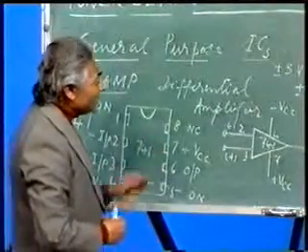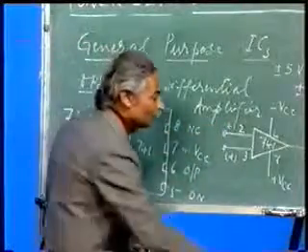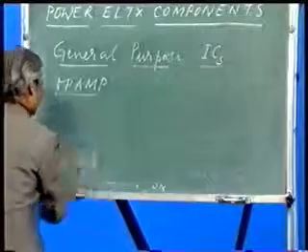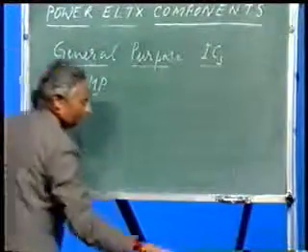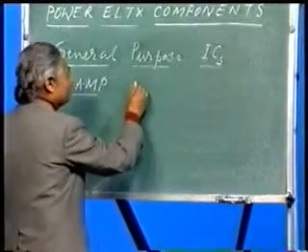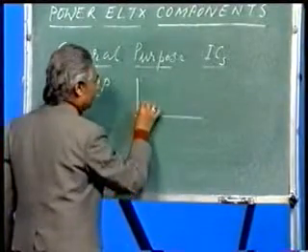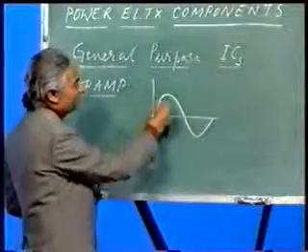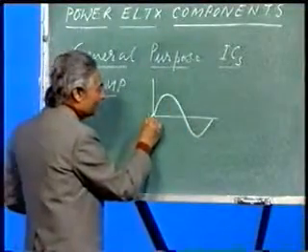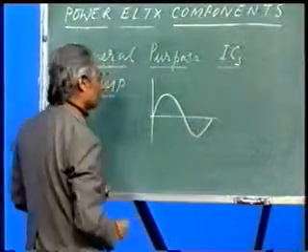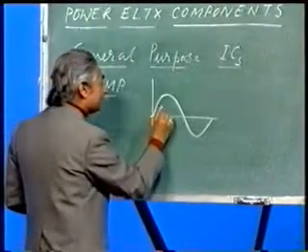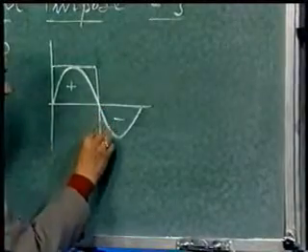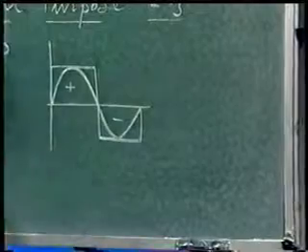Now when I give two inputs here, how does the output look? As I said, I am giving an input supply as say AC. Suppose I am giving only one input, the other one has been grounded and the input is a sinusoidal AC. You see that this is a zero crossing point, this is another natural zero crossing, and this is another. The device will sense it here, and since it is the positive half, it is going to give a pulse like this, then it will come down to the negative, and again become 0.